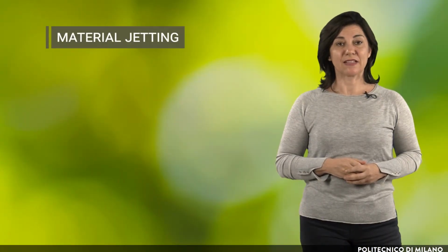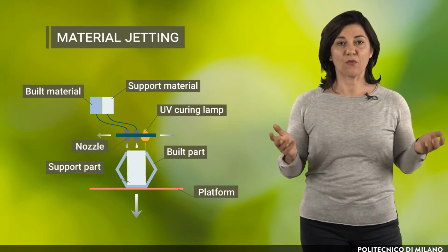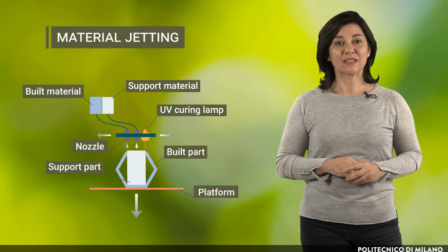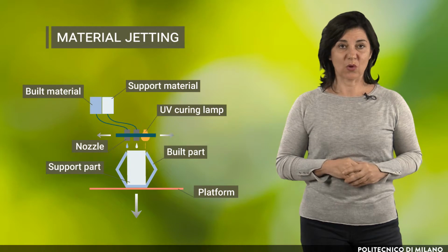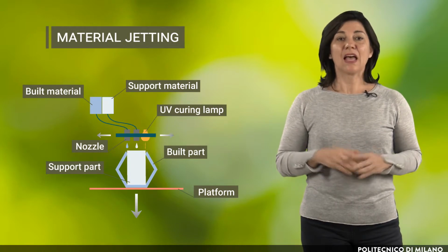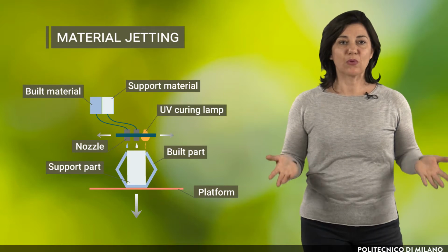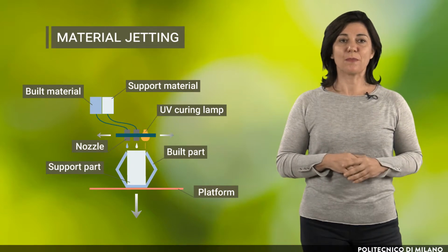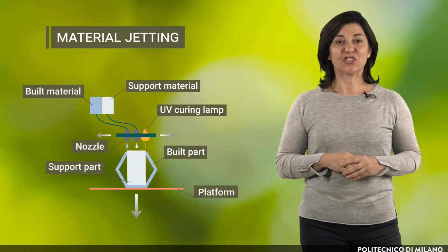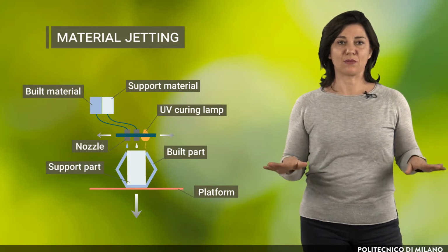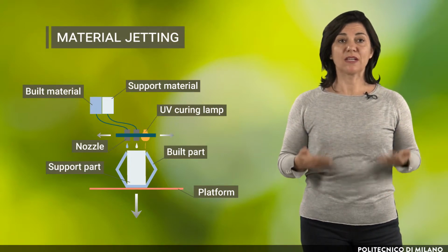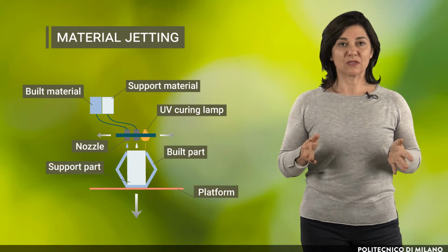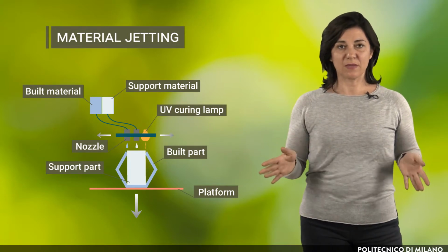Material jetting is defined as an AM process in which droplets of build material are selectively deposited. The feedstock is a liquid photopolymer or melted wax, with or without filler. The binding mechanism is chemical reaction bonding, activated by a radiation light source, or adhesion by solidification of melted material. Material is jetted onto the build surface or platform, where it solidifies and the model is built layer by layer. Material is deposited from a nozzle, which moves horizontally across the build platform.